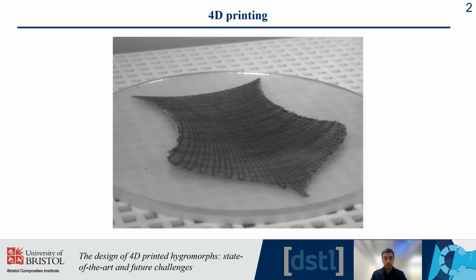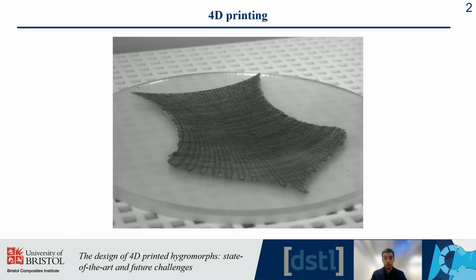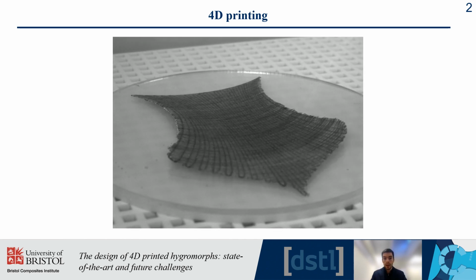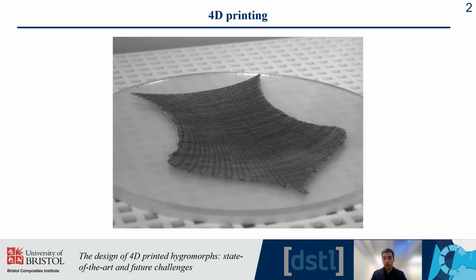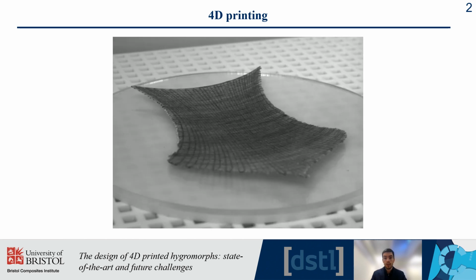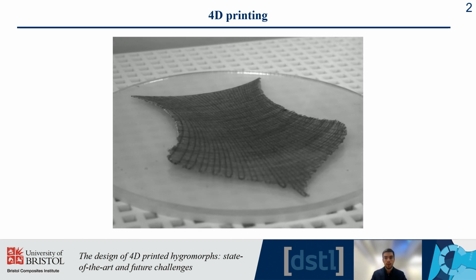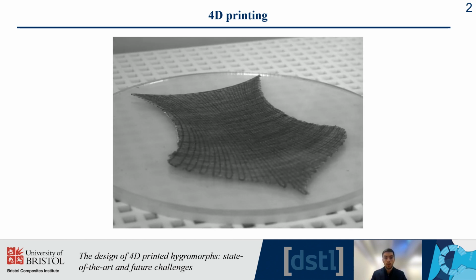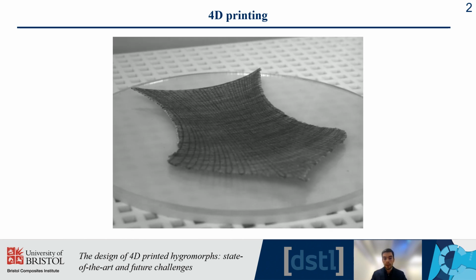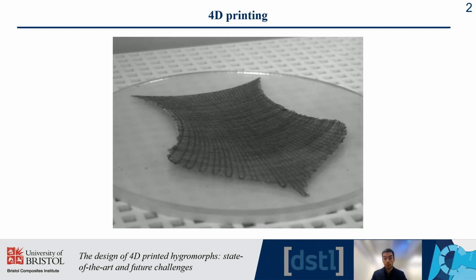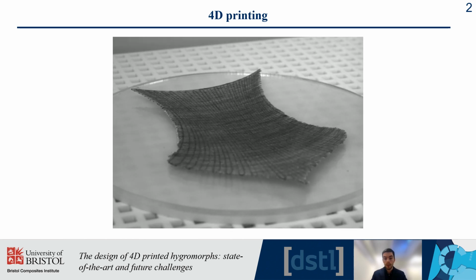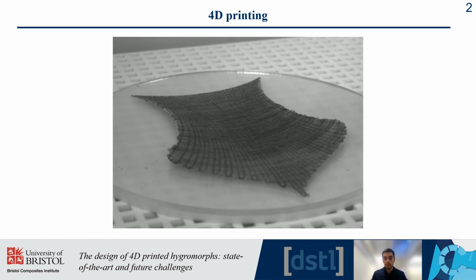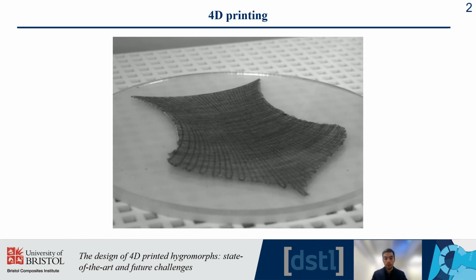An example is given on this slide. On this video you can see an example of a 4D printed structure. It's a 3D printed continuous flax fiber reinforced PLA part, whose transformation is actuation, so bending actuation, when the environmental humidity is modified around it. Basically this part was conditioned at low humidity and then immersed in a high humidity environment, and you observe the actuation on the video.